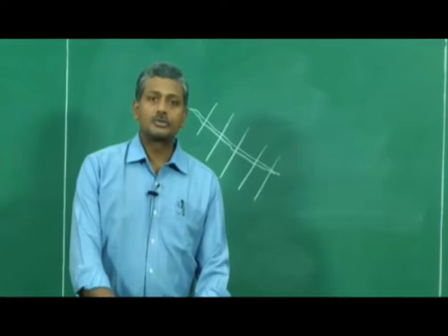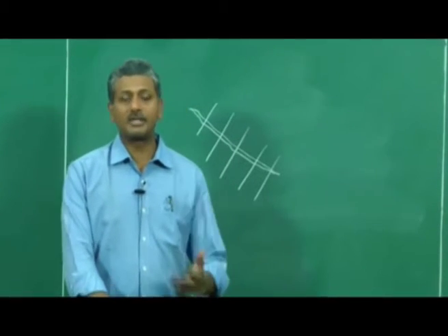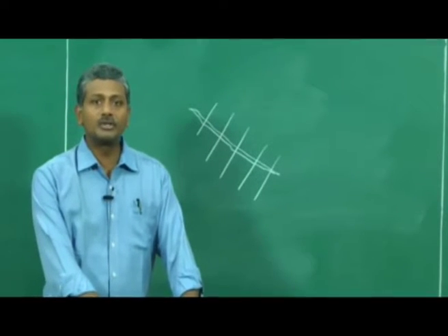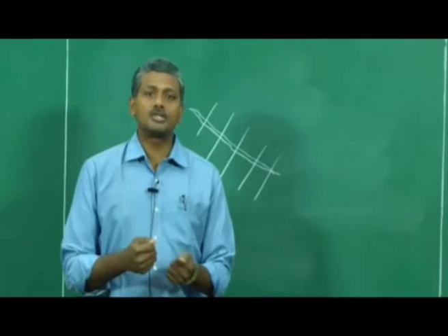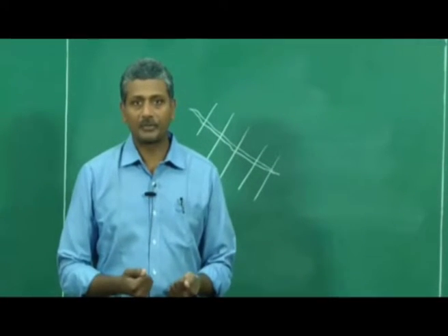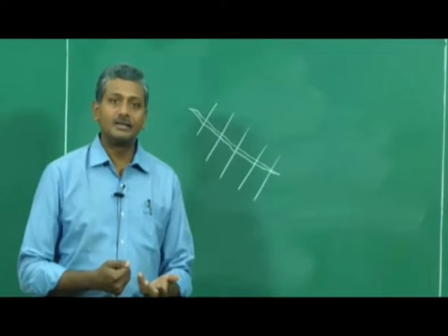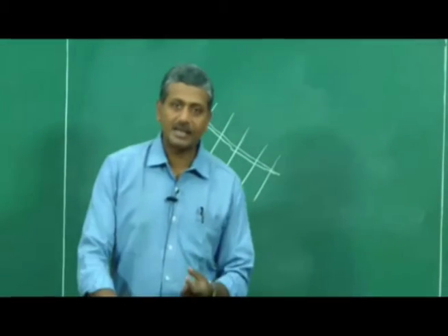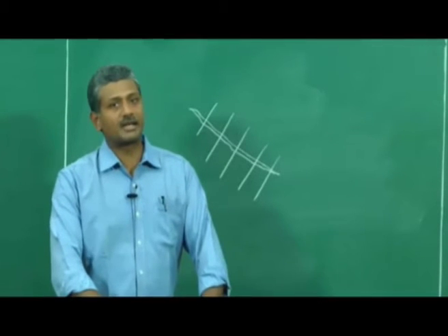Okay. So how is this going to contribute to an increase in compressive strength? Please remember again, the strength was determined by the growth of the cracks at the interface and how these actually coalesce to become larger cracks and ultimately led to failure. Now if I have my interface which is going to crack, my fibers at that size level may not be effective enough to actually control the growth of the interface cracks at all.